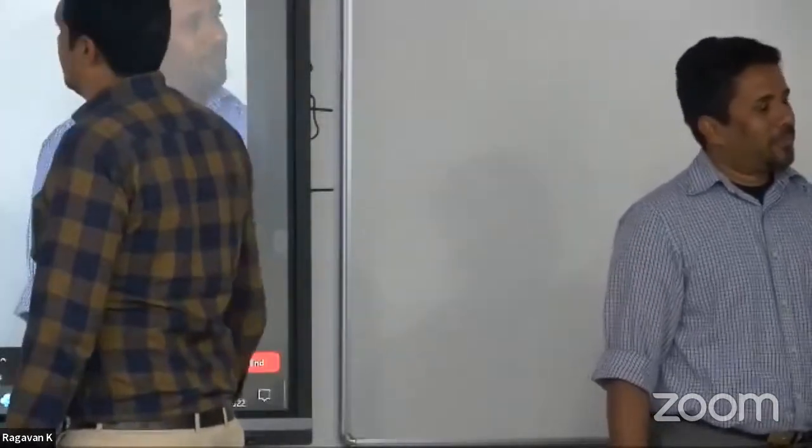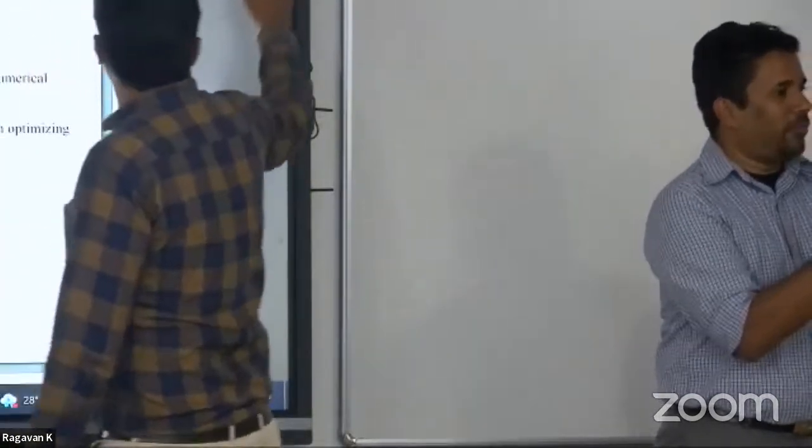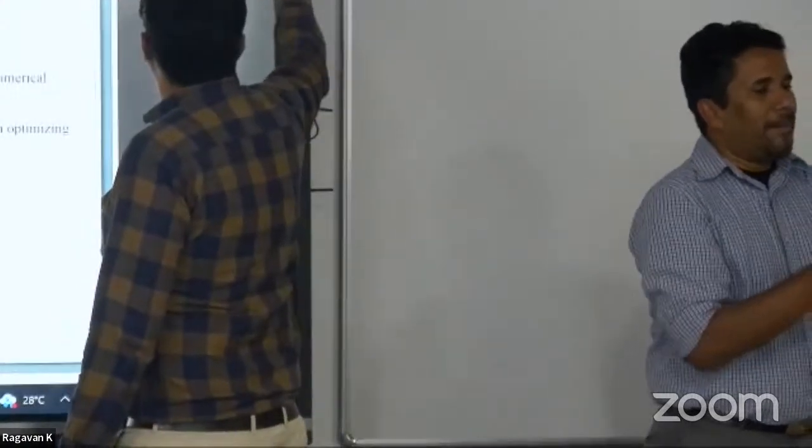Decentering means how does it differ from staggering? Decentering is very similar to the idea of staggering. Basically, you are changing the center of the permanent magnet itself. If you are doing an IPM, you are essentially skewing the center of the magnet rather than staggering, because it's one single piece. So for IPM, it can be a little challenging in general to do a rotor skew.